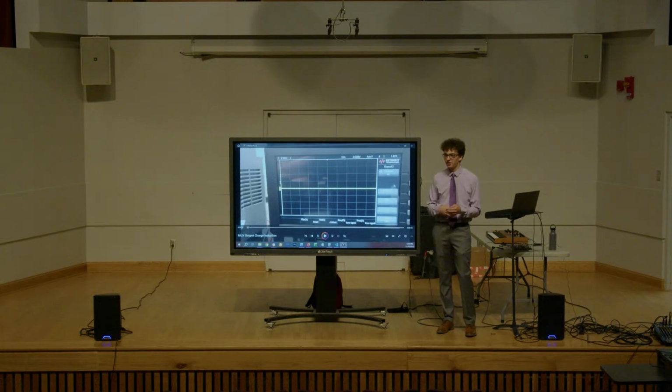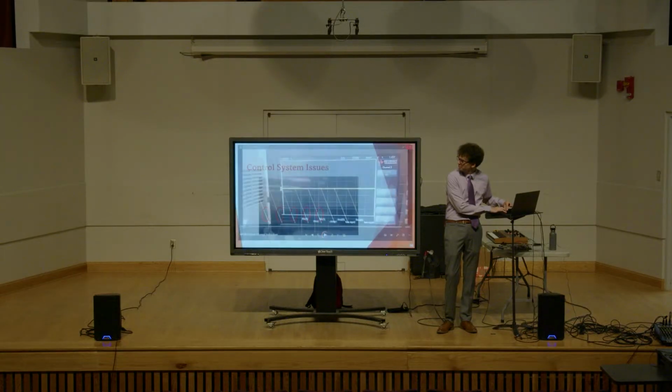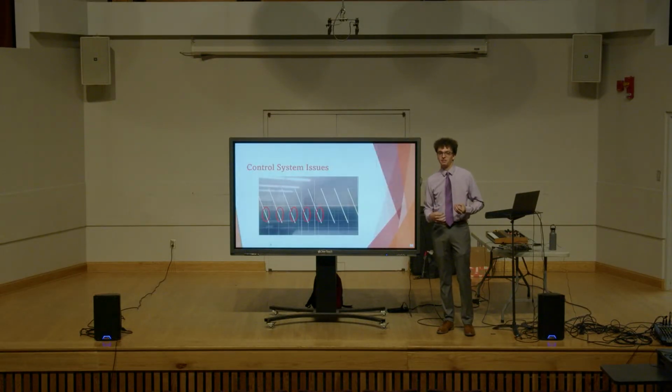And so what I found the cause of this issue was that multiplexers have an internal capacitance. Even if you turn the multiplexer completely off and leave it off for a decent while, it will hold on to that previous voltage that was fed to whichever channel was last fed. So this voltage was being held over from the previous channel into the new channel and was pretty immediately discharging to the proper value that I was feeding it, which caused those noise spikes.